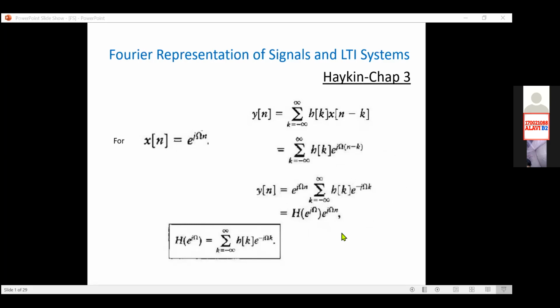In order to develop the mathematical representation of how we will be dealing with Fourier mathematics in signals and systems, we will start from something very simple. We will be dealing with discrete time signals first, then go to continuous time signals, in accordance with the presentation of your book. Yes, sir. Okay, the logic is that we have to select a basis function so that your signal can be represented with the help of this basis function. In our Fourier mathematics, we assume that our signal can be represented by a basis function, something like this. This is sometimes called everlasting exponentials.